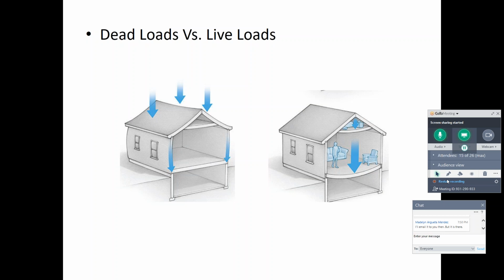As opposed to our live load, which is shown on the right in blue within the house, which could be occupants, furniture, and anything that you're storing in the attic or could be removed when you are, in fact, ready to move. It changes over time. And another thing not shown in this picture, so we do want to consider things like snowfall, right? We have a lot of that around here, or at least where I'm at. And then even rain, if it accumulates in the right way, are adding to our live load. It's constantly in that state of changing.